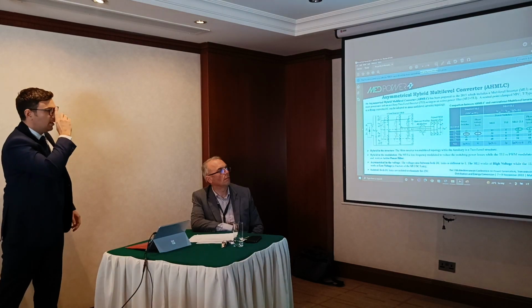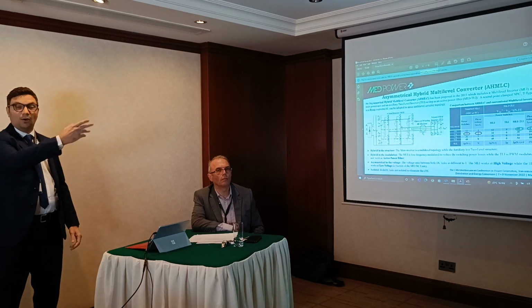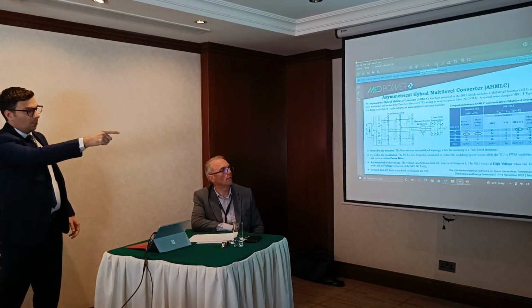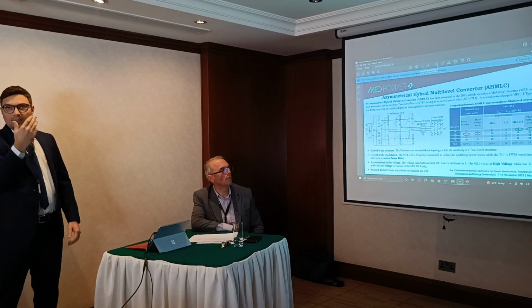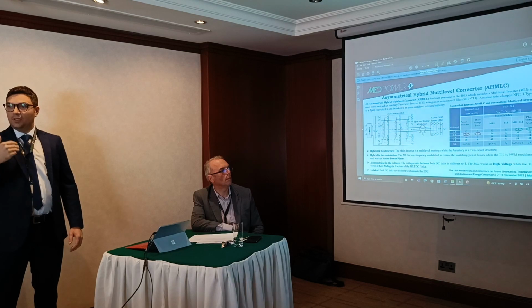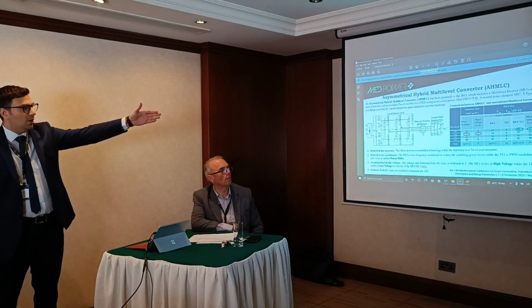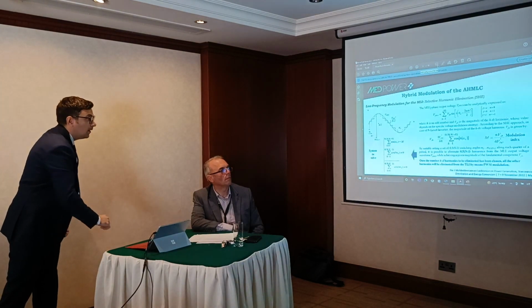In this table, we can see the comparison between the proposed asymmetric hybrid multilevel converter and the conventional ones. In particular, we note that with the proposed reconfiguration, we obtain a high number of output voltage levels by using a smaller number of power devices compared to conventional converters, neutral point clamped and flying capacitor.